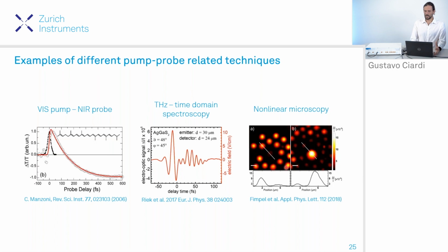Many times, given the high pulse intensity required to generate nonlinear processes for these pump probe measurements, high power, low repetition rate lasers are used, making the duty cycle of the signal very low, and thereby making boxcar averagers a very attractive measurement technique for this type of signal.